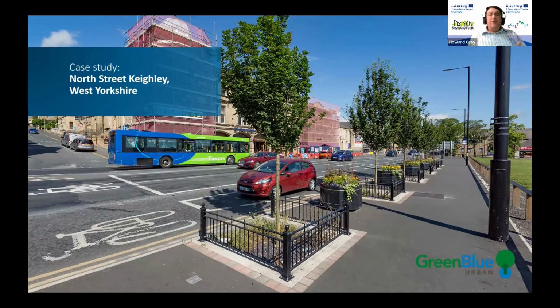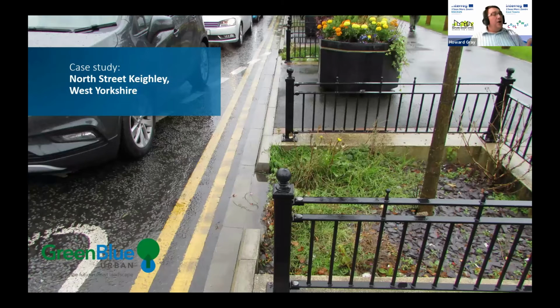One very interesting scheme we did was in Yorkshire, where they extended a road width by an extra lane. They had no drainage. So they did a joined-up six trees, all joined up in a tree pit. The water simply now runs off the road through this tree pit, down through a bioremediation soil, and then infiltrates into the ground below.